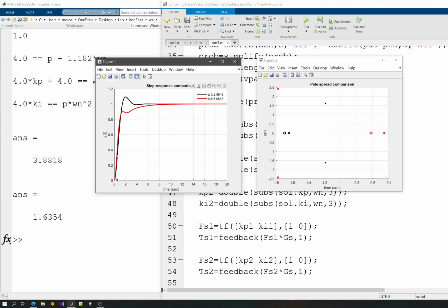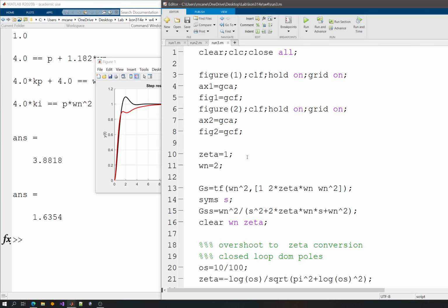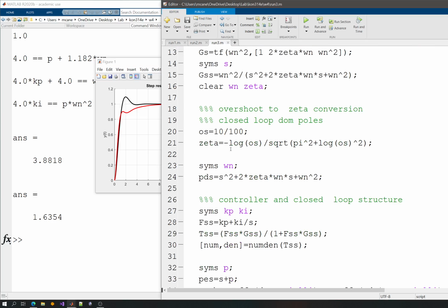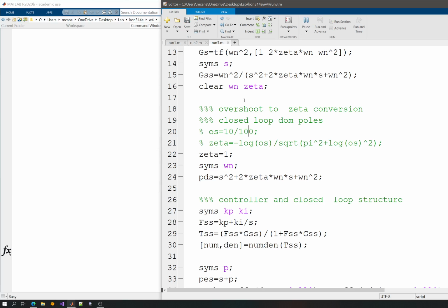But the most ideal thing you would want to have is a first-order system response with a reasonable settling time, because it will smoothly increase and stop at the desired value. Overshoot is not that a good idea, and we can also change that here. Since I have calculated zeta, maybe I want to have zeta equals 1, and I'm commenting this out here. Now let's try this,